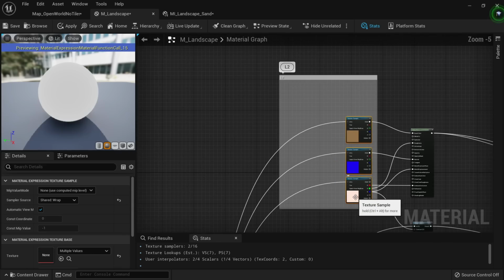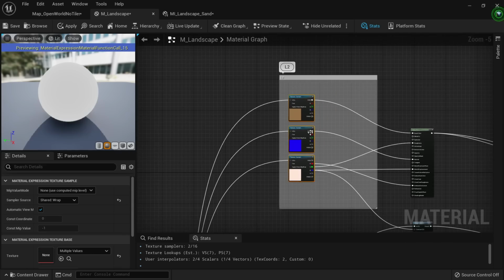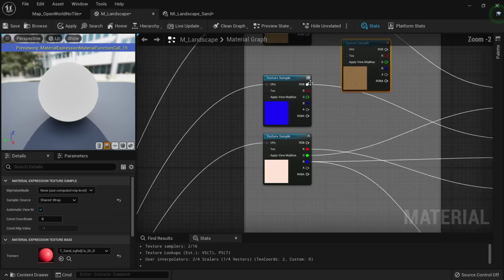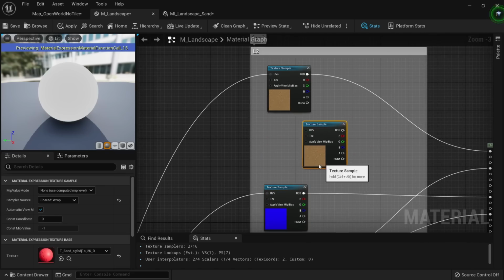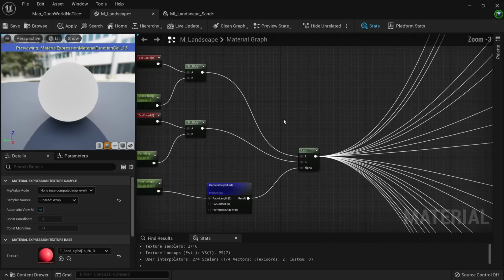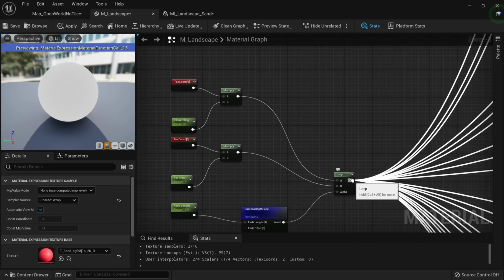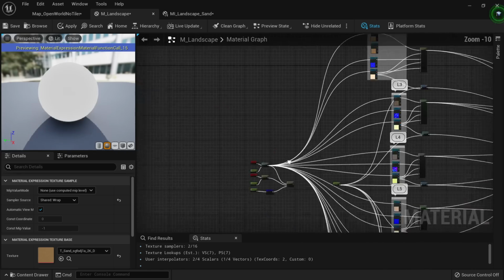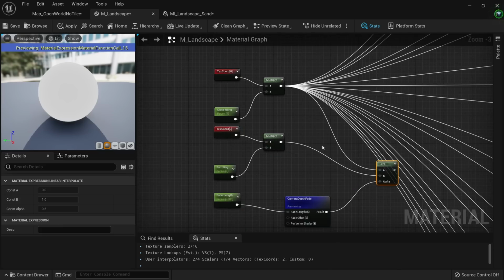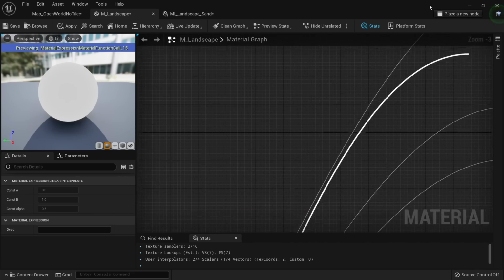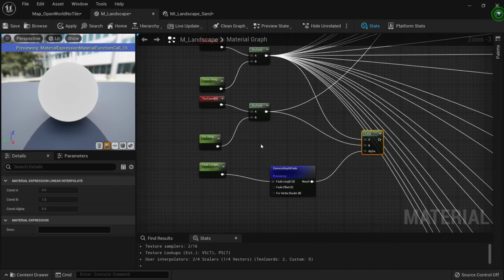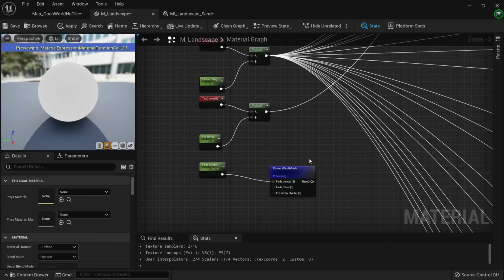So first is sand L2, and this is gonna be my test. So what I'm gonna do is to lerp these two textures actually. So if I check this texture, first this one will be my close tiling. I will like that, okay? But this one will use my far tiling. Okay? So now that I have my far tiling here, I don't need the lerp anymore.